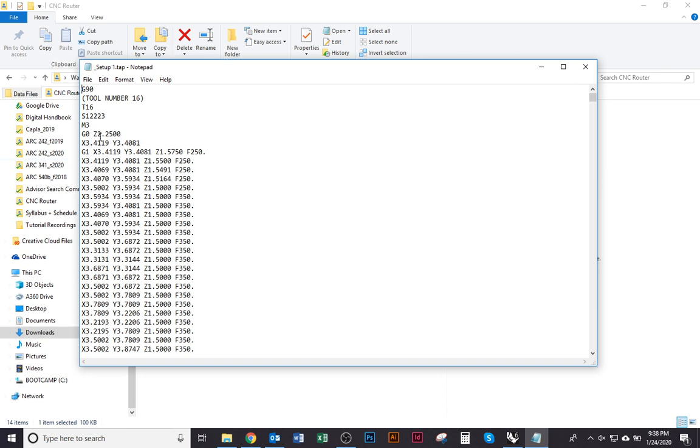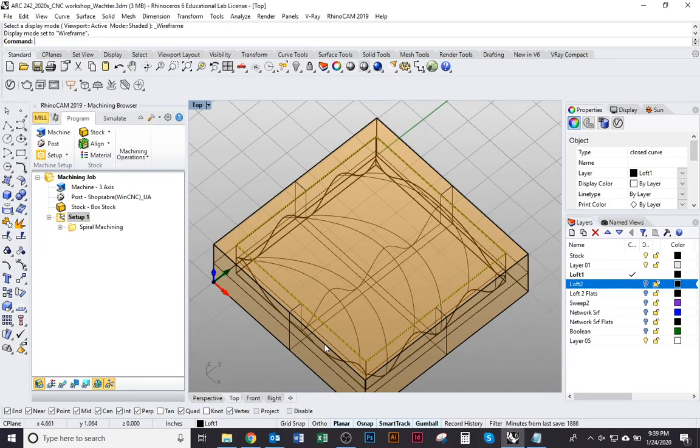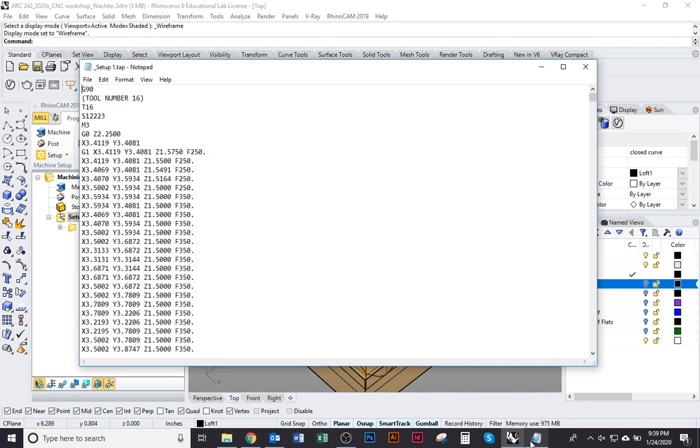What this kind of file is, it's a G code file, which means it's actually just a sequence of X, Y, and Z values. They're basically telling the router what position to go to. So as it's tracing those toolpaths, it's just moving from point to point, one position to the next. And so if we look here at the X, Y, if we look at the Z value, because we zeroed our block to the bottom of the bed, if we were to find any values that were less than 0 Z or negative Z, that would mean that the router is going to cut into the bed. So we generally search this file.